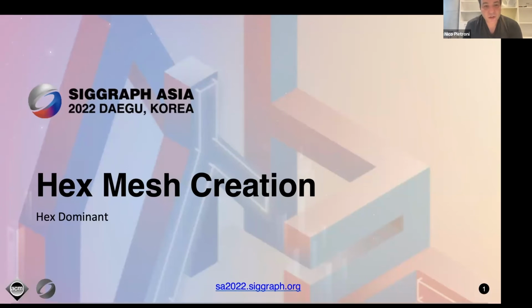Okay, so the next method that we are going to examine in this state-of-the-art report is called X-dominant, and it will group all the methods that create X-dominant meshes. As we showed from the beginning, X-dominant meshes are meshes mostly composed of hexahedral elements, but they can occasionally also include some non-hexahedral elements here and there.